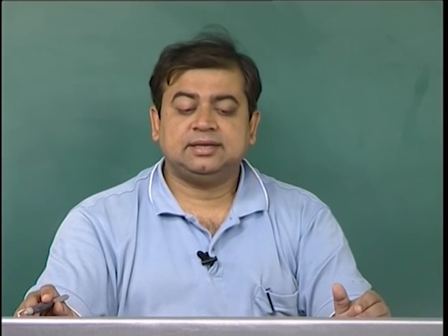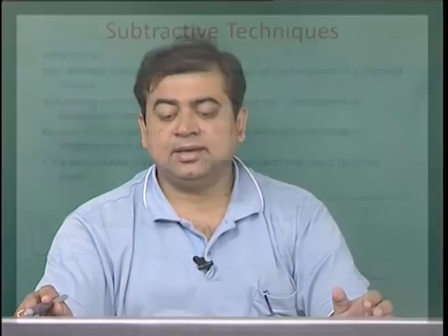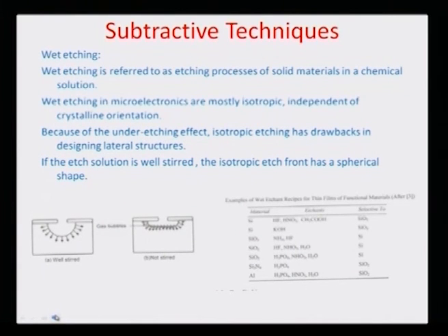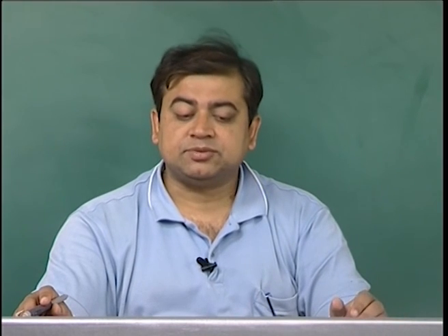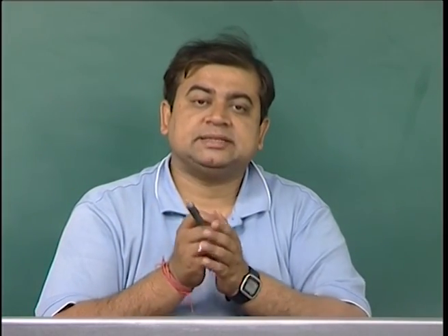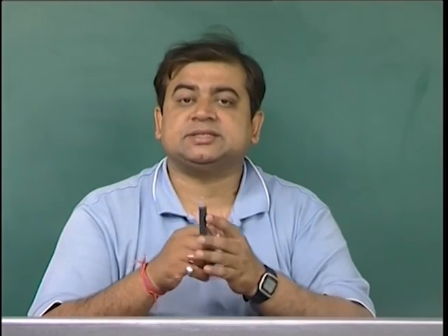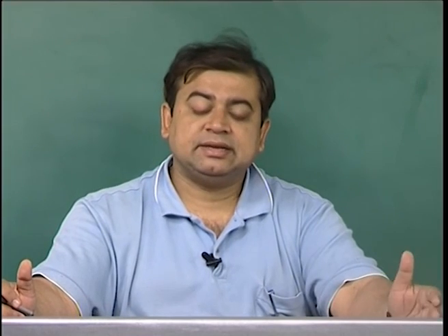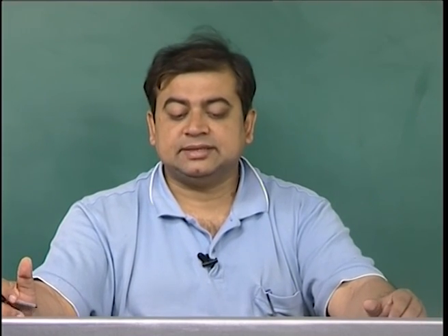And the etching solution is very often used in all the microelectronic processing and also in MEMS processing. So, etching can be divided into two classes. One can be isotropic or homogeneous etching, where the material removal is uniform as a function of the volume, and there can be anisotropic etching, where etching can be in a particular direction, and the differences are in terms of etch chemistries, as I will illustrate in detail in the following slides.